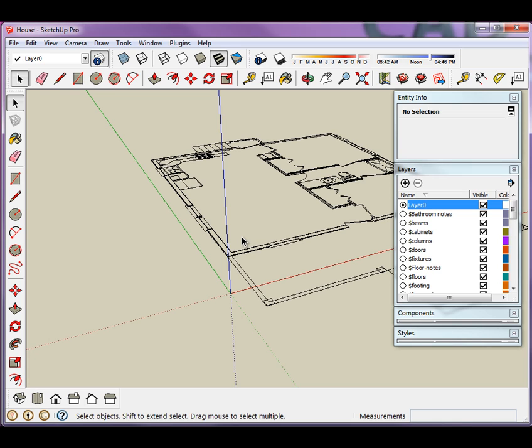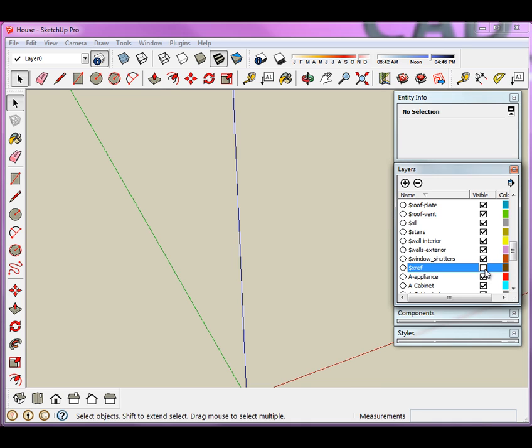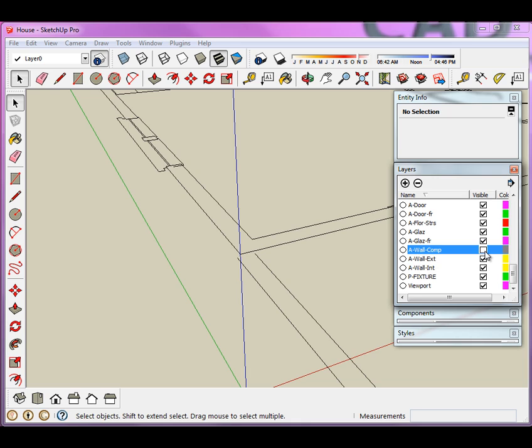Okay, so what we want to do is start with the floor. Notice that with the layer called XREF here, if I look through alphabetically, and I turn it off, the whole reference goes away. But I could also use the AutoCAD layers that you can see below, the layers named with $. Here you can manage the detail, so this might help you when you need to trace around certain entities. All right, for the moment we'll leave it like this.